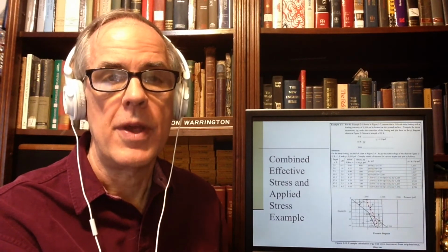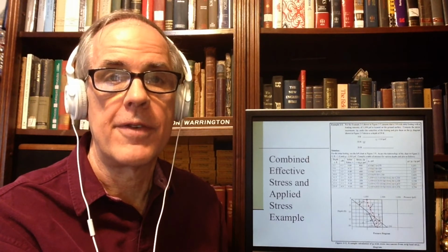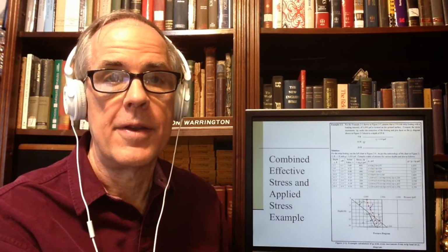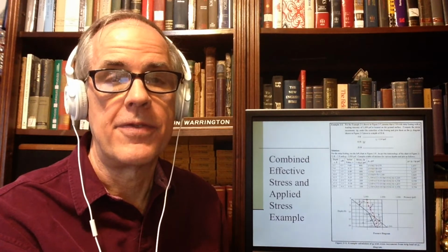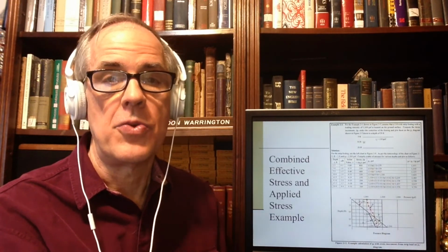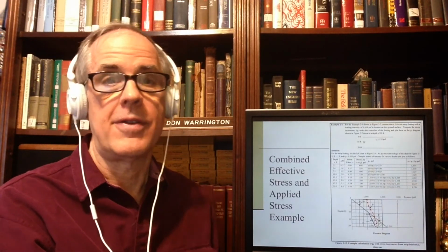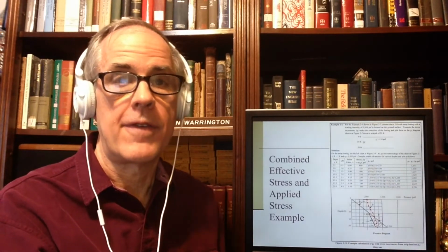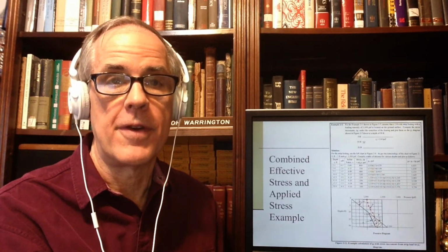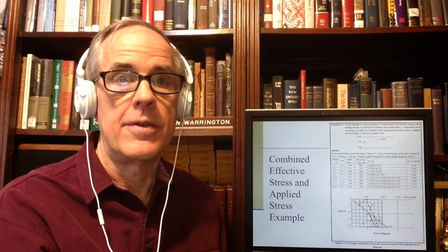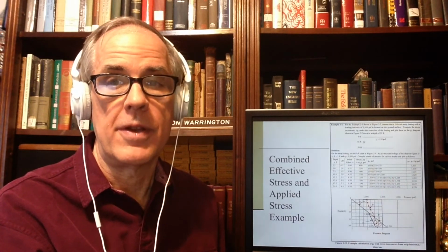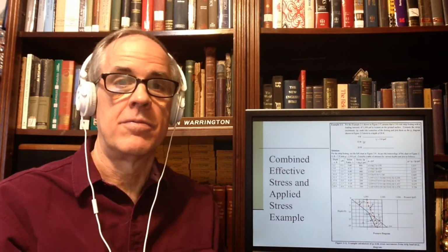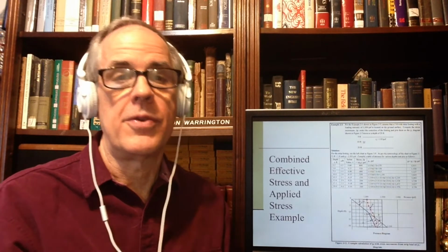Well, you would take the 5 kip per foot and divide it by 5 feet of width, and you would get the unit load. That's how easy it is. So 5 kips, 5,000 pounds, divided by 5 feet, which is the width, is equal to 1,000 PSF. So that's how you get to that.